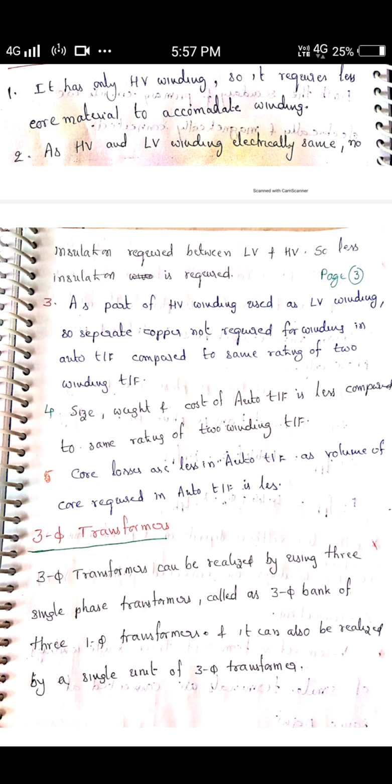Here also step up or step down voltage or currents are available. So if you take 3 windings, you know how to prepare 3-phase, by connecting either star connection or delta connection. When similar ends are connected at one point, star connection forms. And if dissimilar ends are connected together, then delta connection forms. Delta connection provides a closed path for each winding.